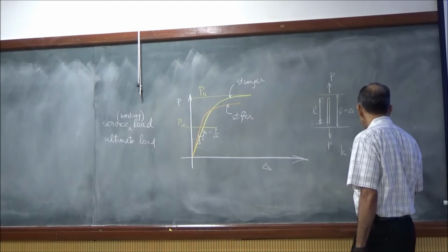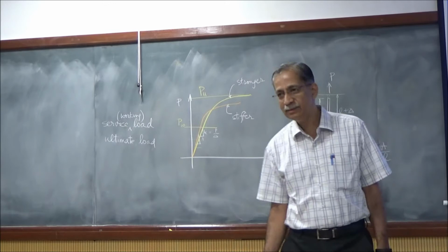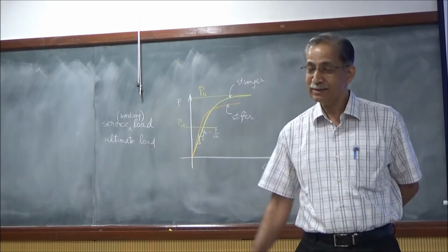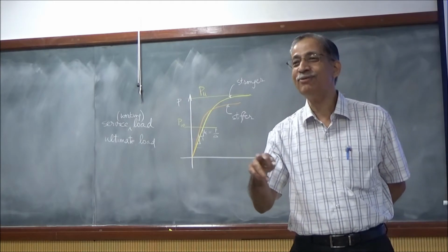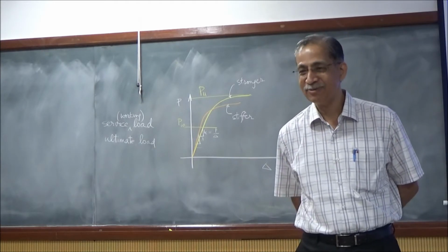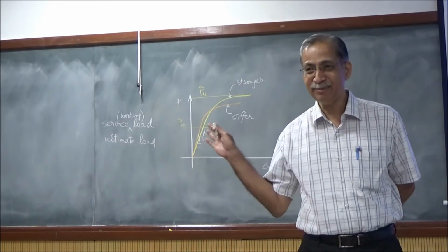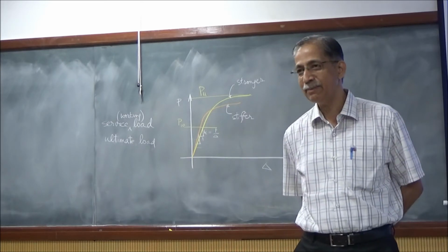I prefer to write it as K. How did you get it? L by 2. Okay, so you are right. Your answer is right. And he is thinking of a factor of half. Where does the factor half come from? It comes in energy, strain energy. It doesn't come in here. Can you go back to fundamentals and tell me how you got this? EA by L?